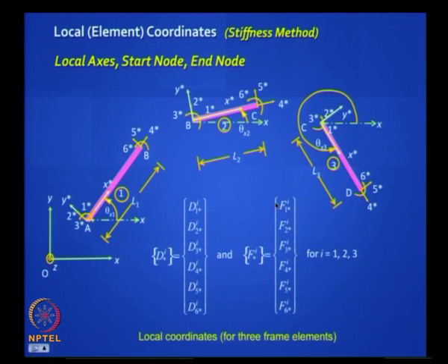So I have a displacement vector 6 by 1, and I have a corresponding conjugate force vector. Does this make sense? Okay, so now I have created a framework with which to start playing my game, but without creating a framework which all of us share and understand and agree to, we will have problems. So is this clear? Are the notations clear? By the way, different books give different notations, you shouldn't get confused, the concepts are the same. So you have to define the local axis, the start node, and the end node, and everything falls into place. The theta is crucial here.